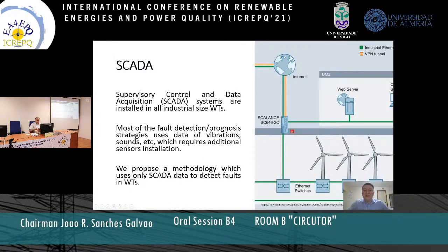On the other hand, we must introduce the concept of SCADA. Supervisory control and data acquisition systems are installed in all industrial-scale wind turbines. Most fault detection and prognosis strategies use vibration data, for example sounds, etc., which requires additional sensor installation. That's why we propose a methodology where we use only SCADA data to detect faults in wind turbines.